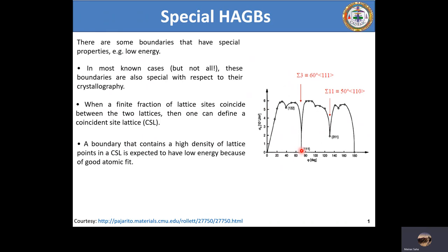If you look at copper, nickel, or even SS304, AISI 304 steel, which is a fully austenitic stainless steel, these materials have low stacking fault energy, and the presence of a twin microstructure in these materials at room temperature is quite common, unlike aluminum. But even in aluminum, there have been reports that we can still see a very small volume fraction of twins in a room temperature microstructure.